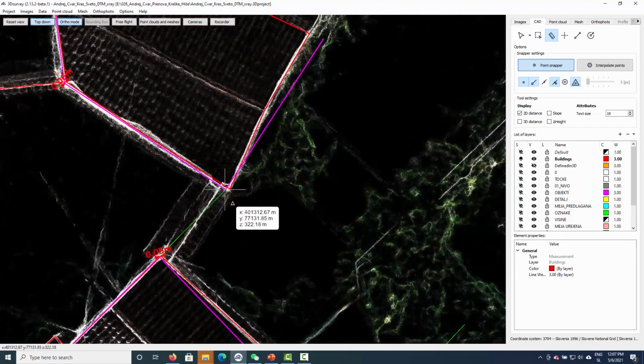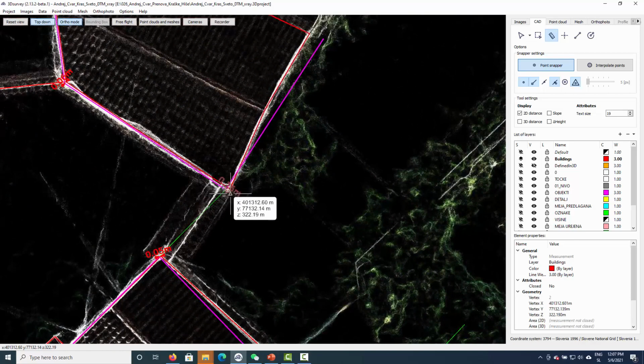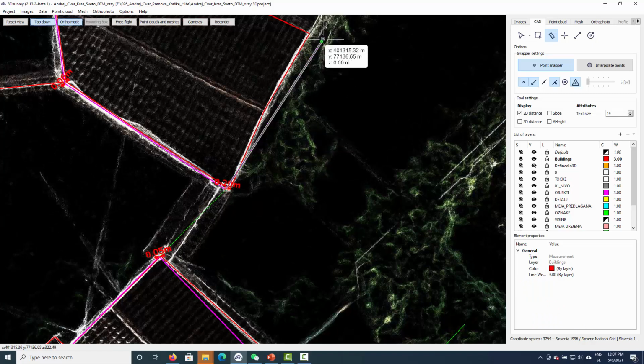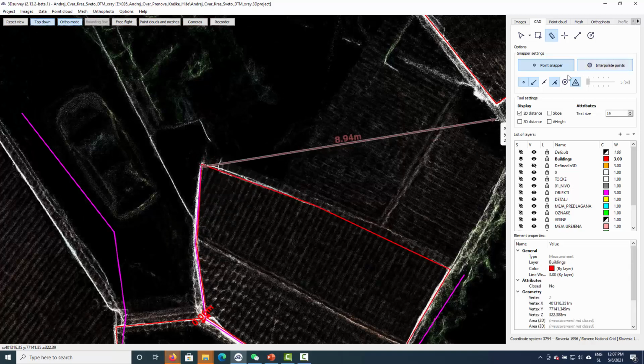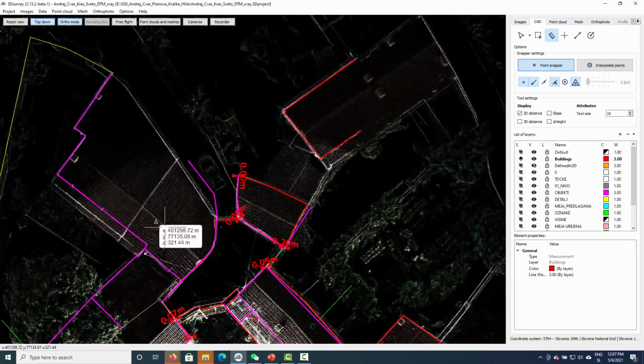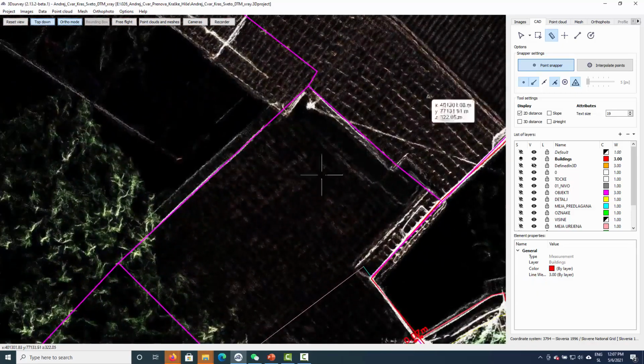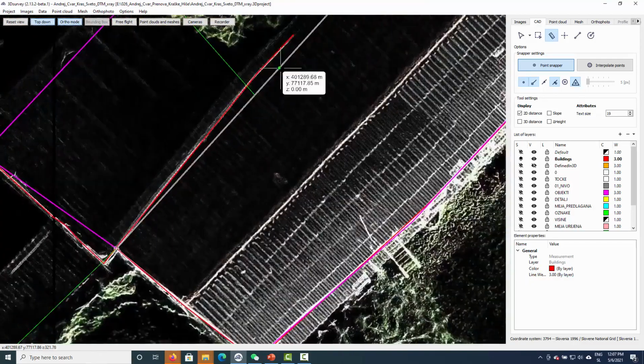Check for this one here, 20 centimeters, but obviously here the photogrammetry is way more accurate because here we see this goes into wrong direction. Check it, for example, here. So I don't want to check the corner, but we should check it like this on the nearest point. Hard to measure because they are too close together.